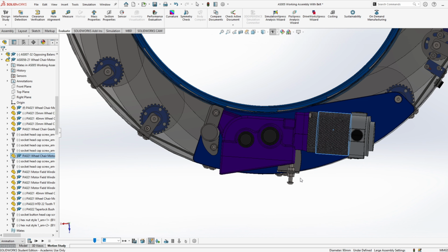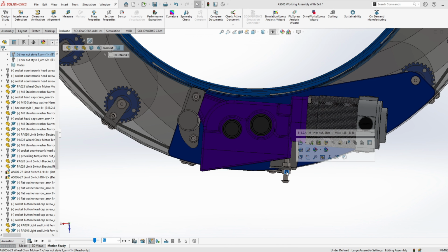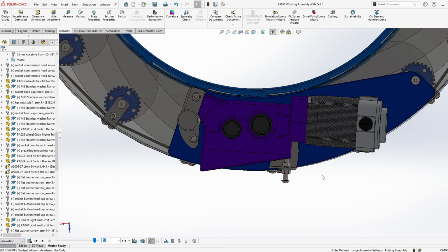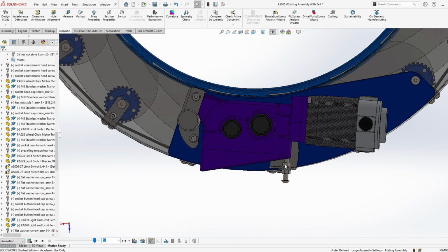To clarify, if I wanted to add more tension to the belt or retract the tension of the belt, I would adjust these two nuts correspondingly. Once the large belt is tensioned using the adjuster highlighted here, or when I find the perfect tension of the belt, it is then locked at this point, bringing these two nuts together.